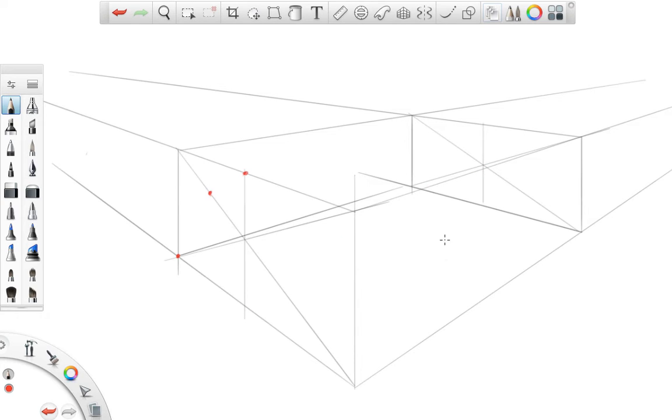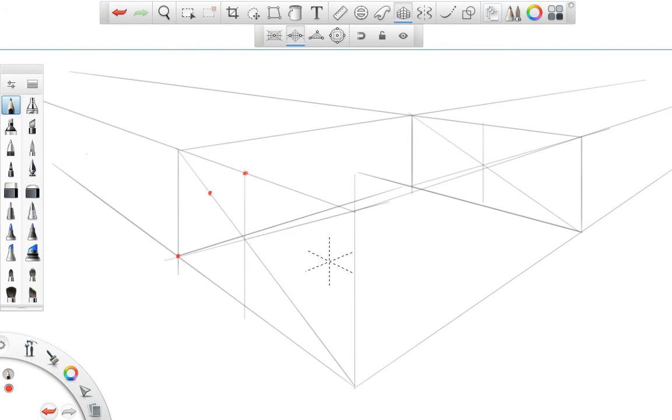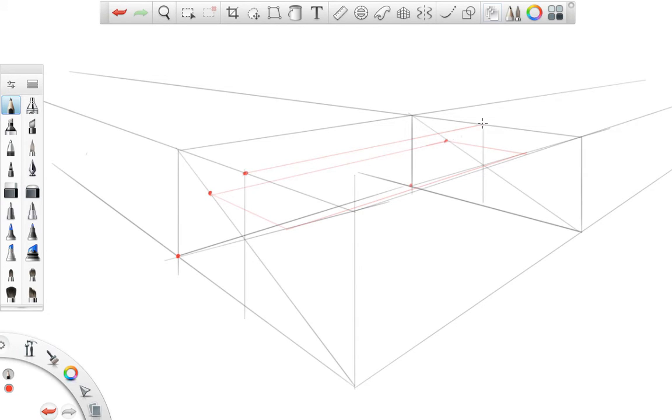So here I restarted the drawing because I just wanted to show you what the best process would be. Now from the vanishing point, I can draw the line, find this point. From here, go to the vanishing point, there, and there, and then there. Also from here to the vanishing point, I found the other points. So number 1, 2, 3, 4, and 5. And here 1, 2, 3, 4, and 5. If we would actually add one more point to it, let's say maybe one here and then one there, it's becoming even easier to start drawing that arc.